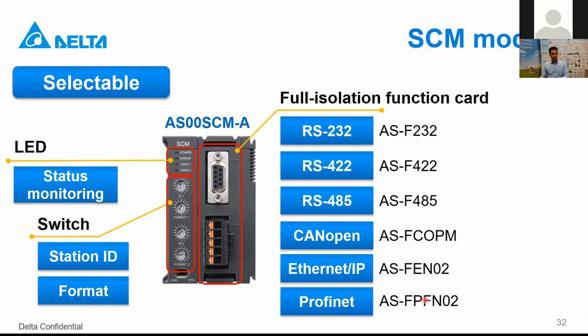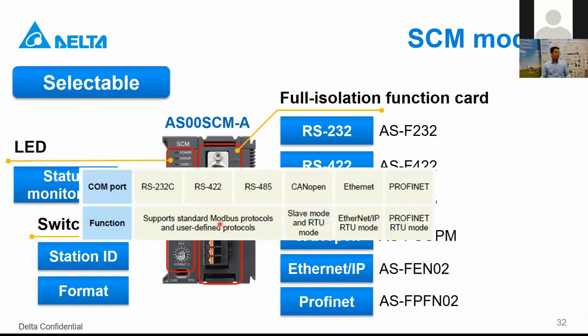Okay, and let's see the functions. For these 3 serial COM ports, it supports the standard Modbus protocol for sure, and user-defined protocols. What are user-defined protocols? Some devices which are not industrial use serial communication without any protocol. It can be called no protocol. For instance, as master, it can be a barcode scanner or LED display.